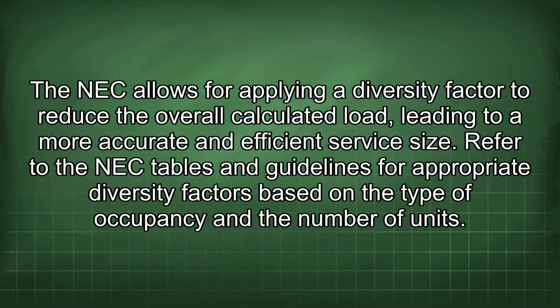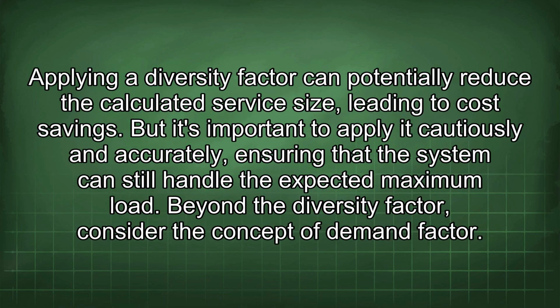Refer to the NEC tables and guidelines for appropriate diversity factors based on the type of occupancy and the number of units. Applying a diversity factor can potentially reduce the calculated service size, leading to cost savings. But it's important to apply it cautiously and accurately, ensuring that the system can still handle the expected maximum load.